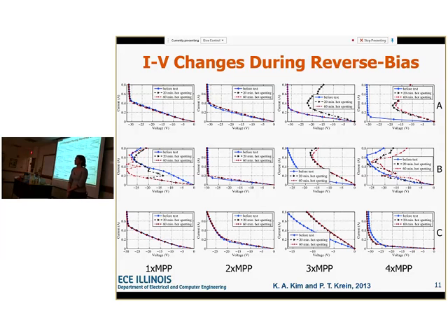So you just increase granularity then. The short answer would be to decrease the string length, make them maybe 3 or 4 cells, and then you'd be pretty good. If you really want to be safe, you'd do every single one, but studies have shown that ends up being more work than it's worth. But good question.